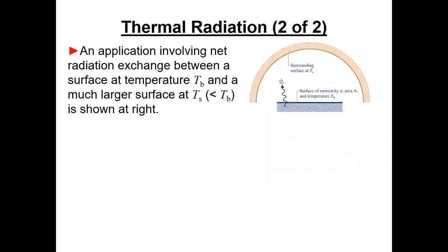Okay, so you've got two temperatures up there, and that epsilon, a lowercase epsilon, is the emissivity, and that's a surface property of that slab that's laying down there. Okay, and again, emissivities can become complicated. They can actually be directional in nature, but at this level, it's just a constant that applies to the surface. And it defines how efficiently that surface can radiate energy.